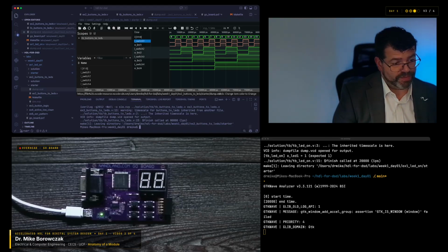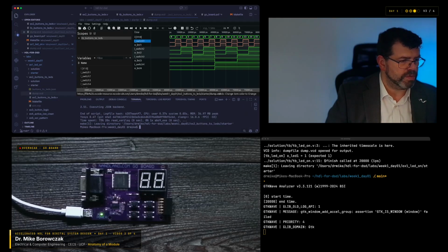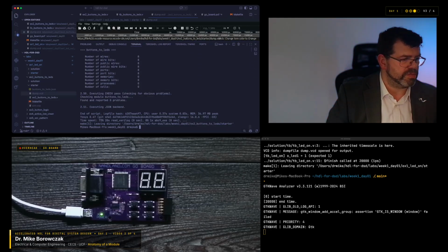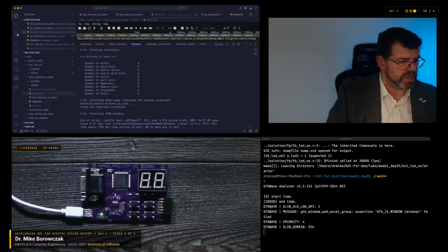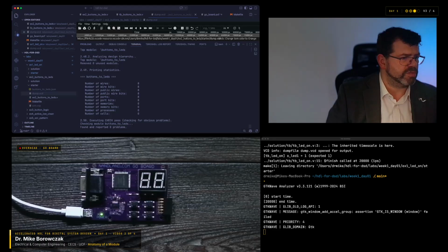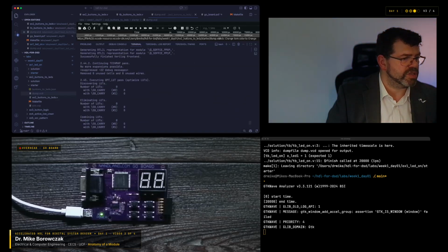So now let's program it. So the path we should take is make example 2. And what we should do is we should do synthesis first, make sure that that passes. And what we get here is this output that does say found and reported 0 problems. So ultimately this did work in terms of being able to map this. We get some output here in terms of statistics. How many wires did it take? Basically how many ports, other things. If we scroll up far enough in here, we'll also see potentially the number of LUTs.